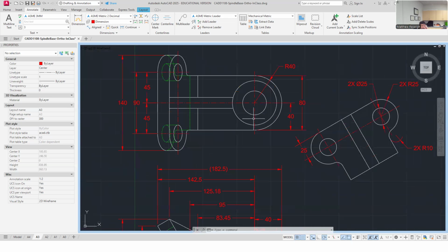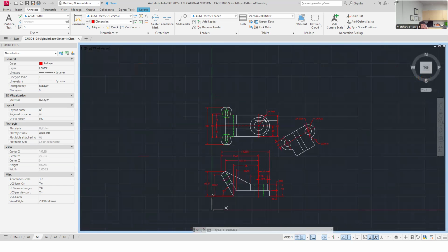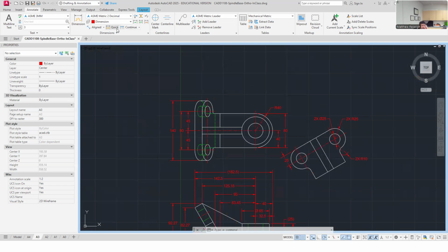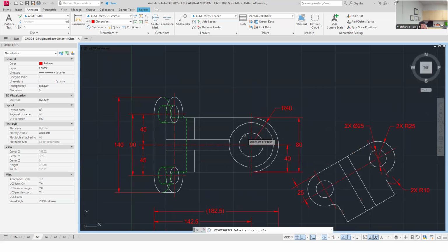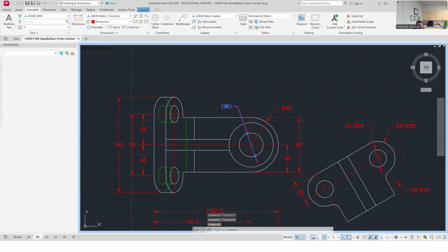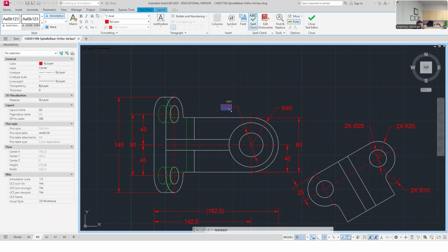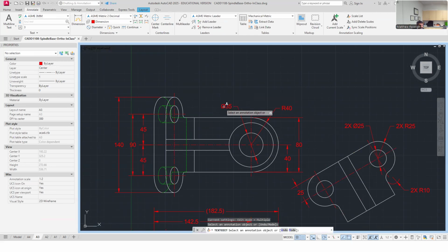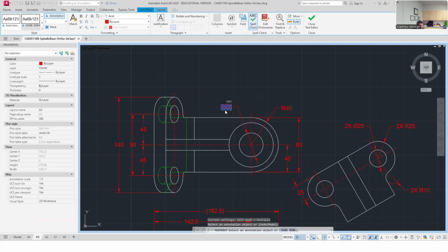It's got an inner bore though, part of it. So I need to size the inner bore, and I can't do that here. It's hidden line work. So I'm going to size it up top on the top view as a diameter. So this one is definitely a diameter, right? And there's just one of those, 35 through. This is the one that I might add through all to. It wasn't clear on the assignment sheet if it was. I've drawn it as a through all, so I'm going to notate it as a through all.